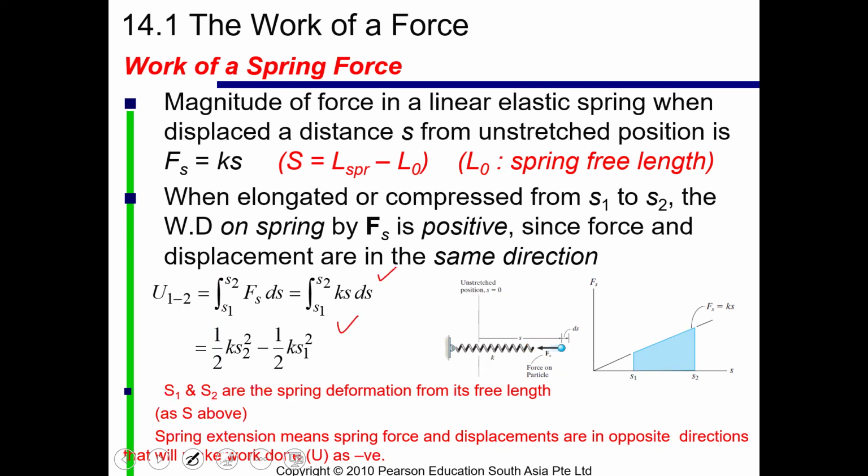This is right because the work done will be positive in this case. So this is a small tricky thing that you need to remember: you always need to see the force in the spring and the displacement happening in the spring, so that you can realize whether it is a positive work done or a negative work done. In case of compression, as a rule, remember that this is a positive work, where both are in the same direction.